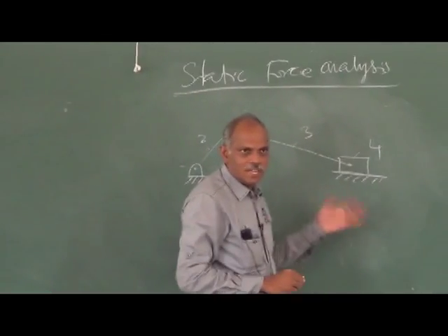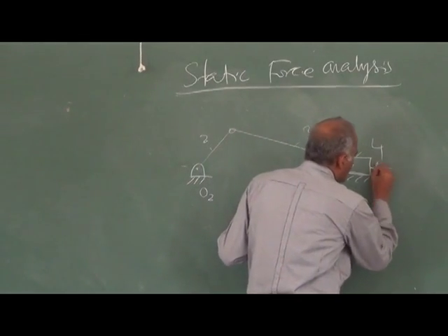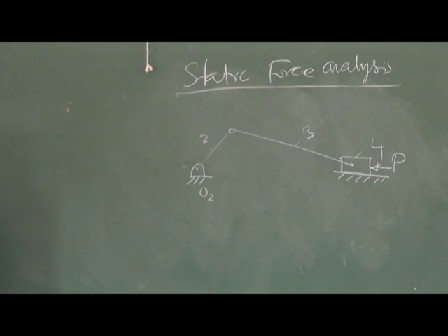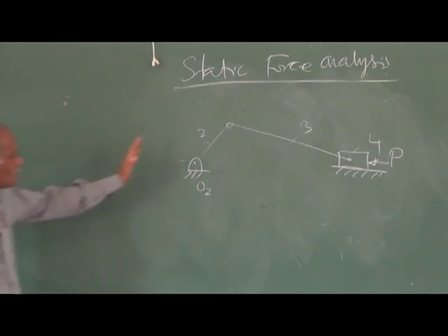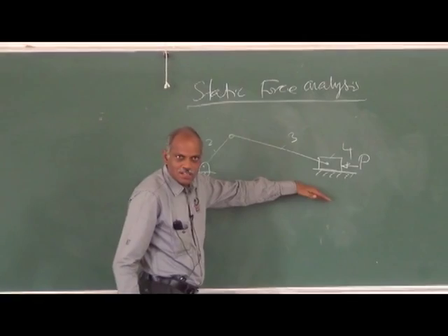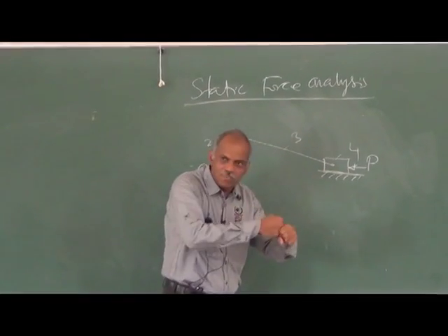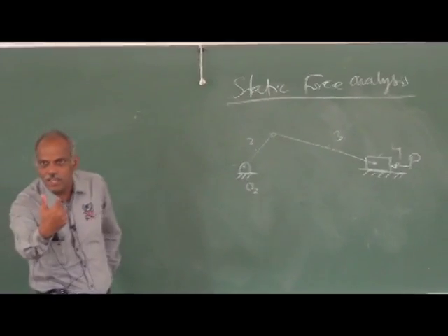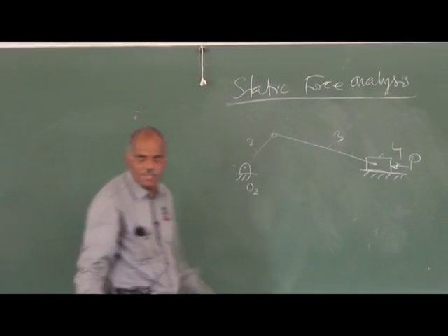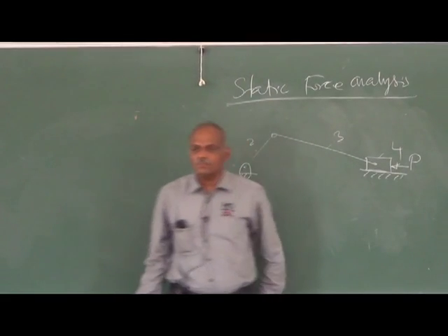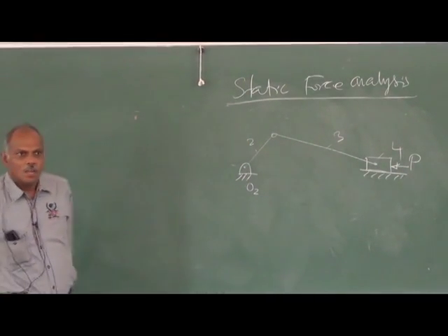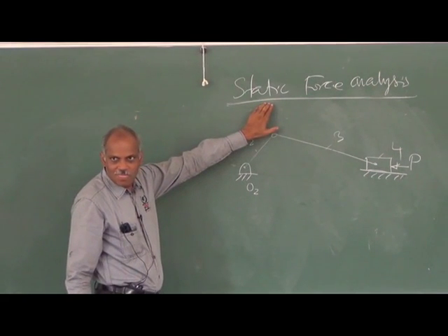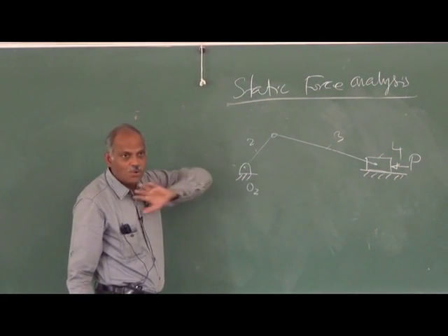Here, in the static force analysis, let us think there is a force P acting on the piston. Or using a slider crank mechanism, you are using this to crush something. Now it is holding something, so that is offering a reaction force of P. But since it is a static force analysis, this mechanism is not going to move.